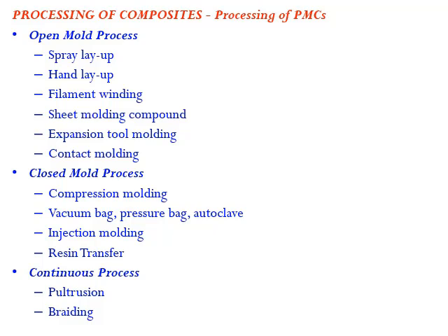Okay, whether it's an open mold or a closed mold. Open mold means we have a mold whose top is open to the atmosphere, where we pour the liquid matrix and place the reinforcement, and it gets hardened, and then we get the proper shape. It means the mold decides the shape of the component which you are going to get.